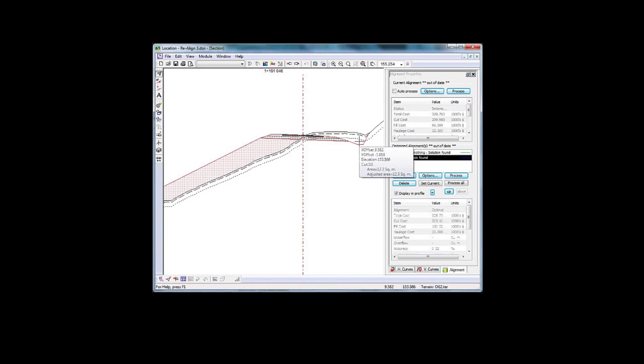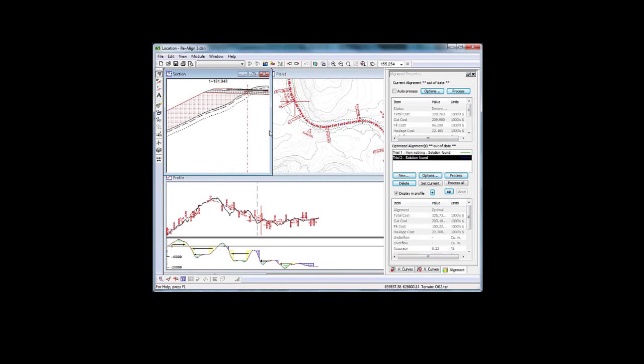So this little bit here, it's cutting rock. Above that, it's cutting glacial till, or, well, we're actually in the roadway here, so that's probably a poor assumption. But we've got some stripping going on. This is a realistic road design. It's the optimizer taking into account all of those cross-sectional areas and volumes when it's doing its work.